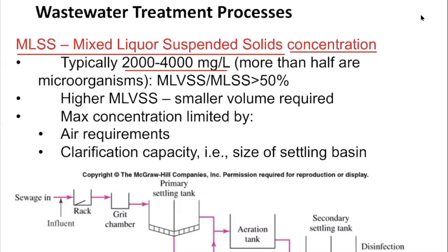And within these suspended solids, or the MLSS, more than half of it are actually microorganisms. Okay, so what that means is that the MLVSS divided by the MLSS is higher than 50%. So you can see the magnitude of these bacteria inside. Actually half of them, or more than half of them, are just bacteria that we feed in to decompose these organics.